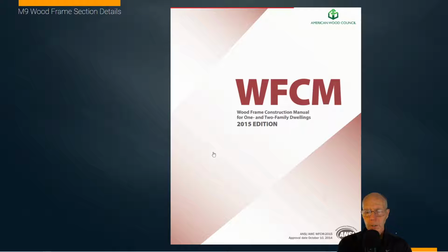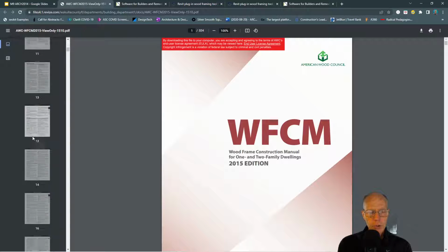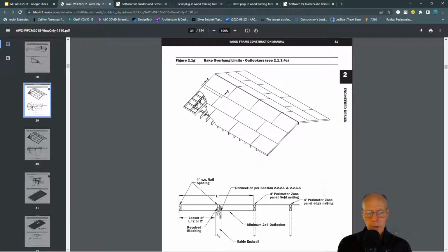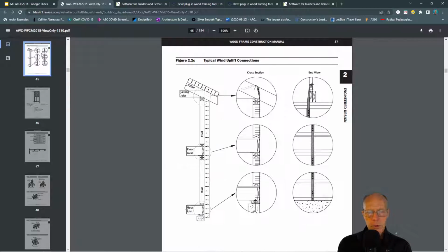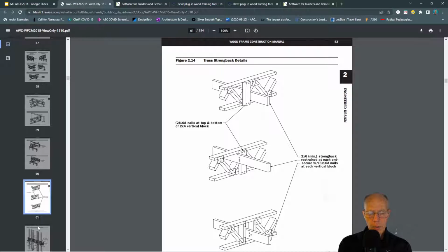I've got this one last link that if you click out, it'll take you to a wood construction reference material. I'm not sure they'll mention this in construction tech, but this is really a huge, rich document that details all kinds of ideas about the way wood framing systems come together and are constructed and detailed. Here's an idea of what would be wind loads on roofs, in this case wind loads and uplift loads, but you can see this idea about how we're creating these sections and labeling these components, and just tons of details that would show you how you would construct these.